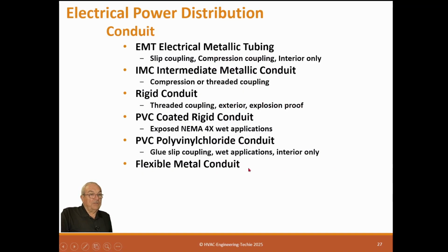Metal flexible conduit requires a ground bond wire, especially special slip couplings. So if you're going to use flex conduit, then you need to put a ground wire in it, because on the other systems, the metal conduit can be the ground, but on these it cannot be.